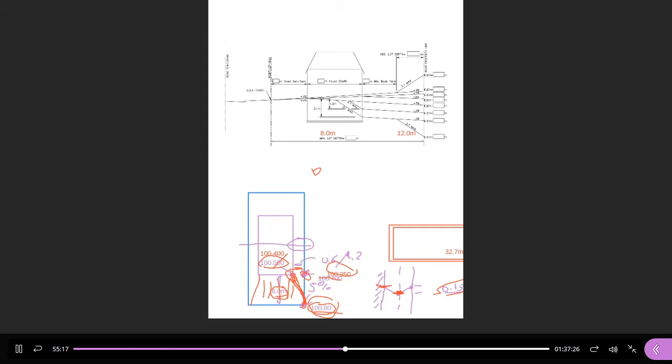Okay, let's deal with the front drainer. Suppose the elevation at the back of the lot is much, much higher than the front. There's your front draining lot. There are 3 categories of front draining lots shown here. There is a minimum backyard. So instead of starting at 2%, I'm trying to go as high as possible at the back. So instead of using 2%, I'm going to use 3%, right? So I'm going to use this one, not this one. I want to start off a little bit steeper so that I can start to come up faster. So I'm going to use 3%.